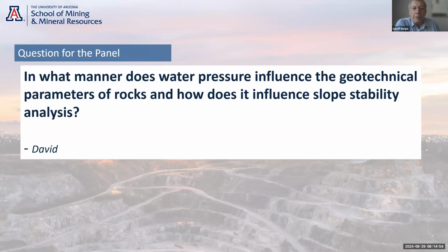There is another component of this which is often ignored and is much more difficult to quantify, but I think in the geotechnical community, we're seeing this as becoming more and more important. And that is the driving force of the water. So if you can think of a slope with, let's say, a tension crack 10 meters behind the slope, and that tension crack dilates because the slope relaxes a little bit because you've mined the material above it.